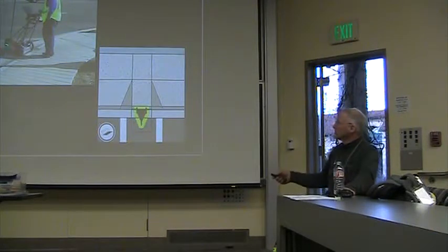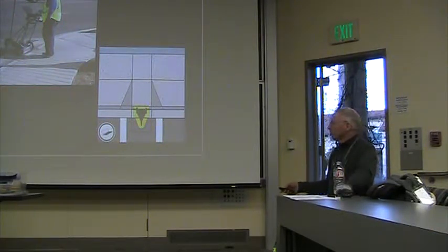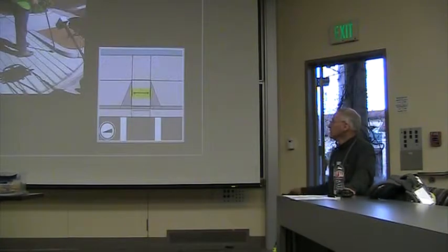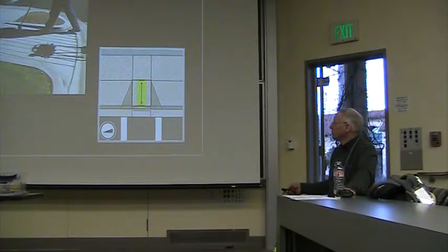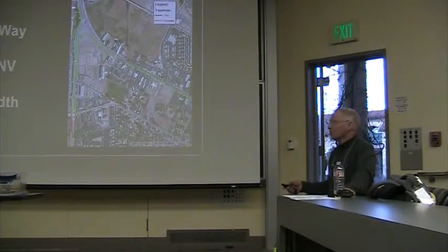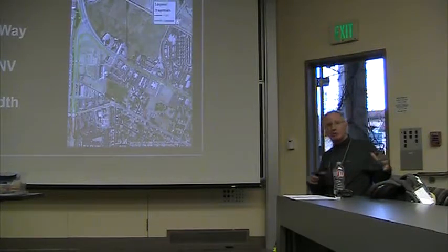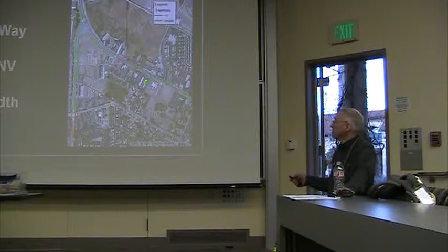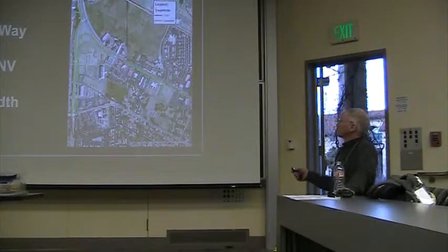And there we're measuring the gutter grade, which is important. When you go through that gutter from the ramp, you can hit your footrest and get thrown out of your wheelchair really easily. Then we use the wheel to measure off the width of the panel and the length of the panel. What we can do is take all this data and put it into GIS maps. A GIS map gives you a symbol and shows you what's going on. Like this one's showing everything that's green is compliant in the width. Everything that's red isn't wide enough.